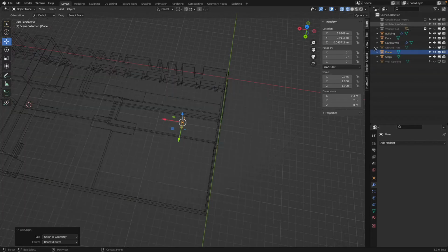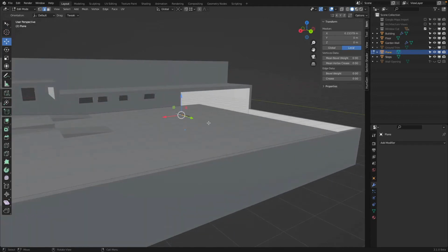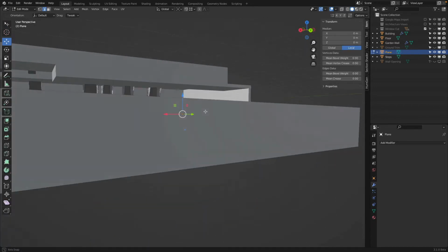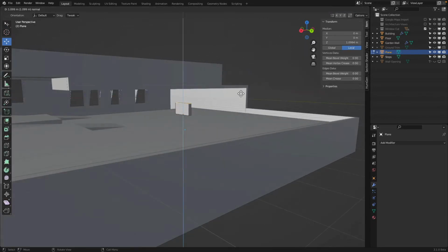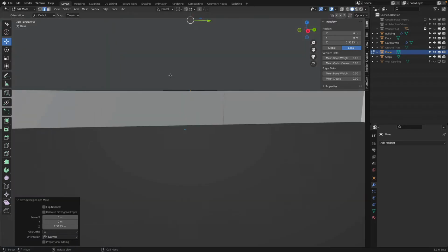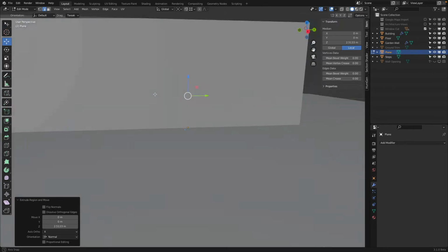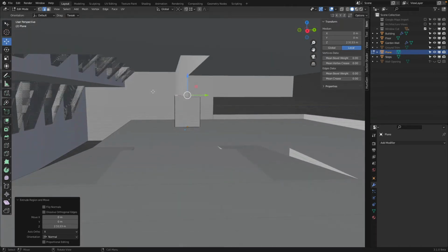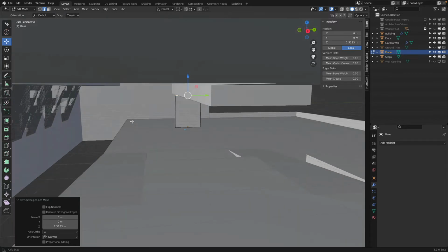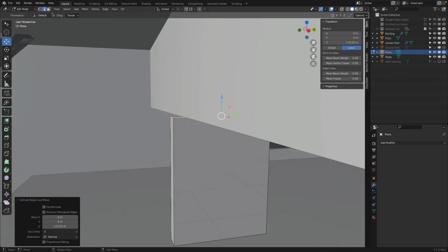Now this I would like to move down and snap. Very good. Edit mode, A, select everything, E, extrude up, Tab, and snap. So now it's a question: to what degree is our model actually correct? Oh, look at that hole here. Well, we have to move this over. Totally forgot.